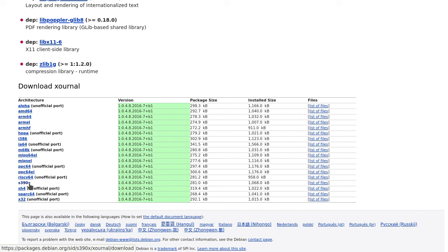It's just 5 computers, okay? Why would that pop a circuit breaker? How much power is one computer using? We are talking about gaming computers. So these are not laptop computers designed to run on battery for 10 hours. What is the usual power supply capacity for a real gamer's computer? 750, 800 watts. Like 750 watts. 7 to 800, yeah.